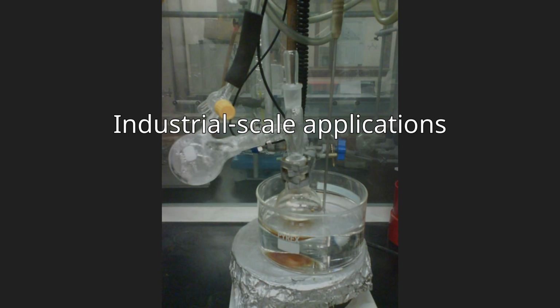Industrial scale applications. Industrial scale vacuum distillation has several advantages. Close boiling mixtures may require many equilibrium stages to separate the key components. One tool to reduce the number of stages needed is to utilize vacuum distillation.